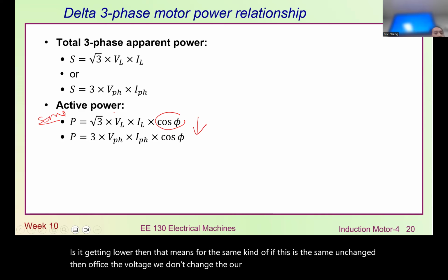So that means our no load power, after we remove the R1 losses, must be some kind of rotational losses due to something. That loss, in the open loop condition, must be core loss plus some frictional loss or windage loss. So that's how we can get it.